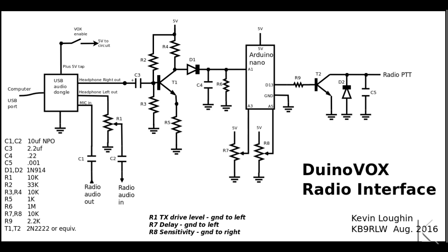Now C1 and C2, I used a couple of non-polarized capacitors because I had them available, but you should be able to use regular old electrolytics. It shouldn't matter which way the polarity is, the audio is going to pass right through.